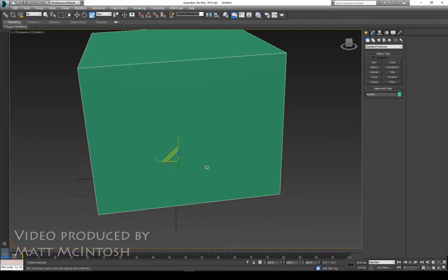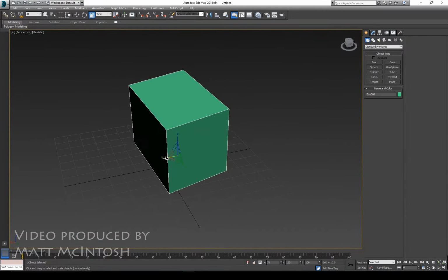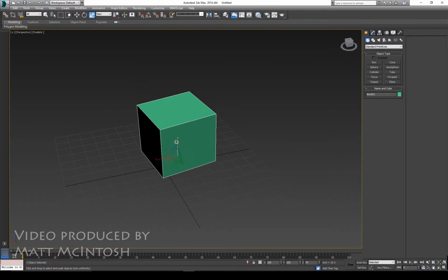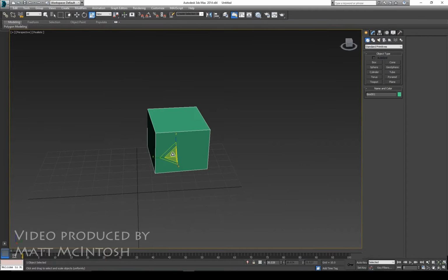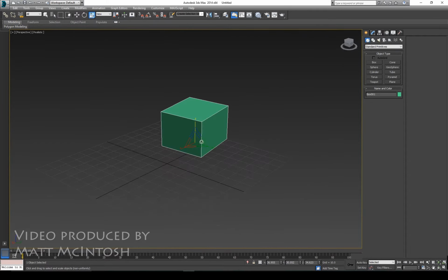So that is mapped to the R key on your keyboard, and that allows you to scale your object in a specific axis, like so. So by using a combination of those things, you can start to move your object around, you can rotate it, you can scale it. But what if you want a little bit more control over that? Because I'm doing that freeform.